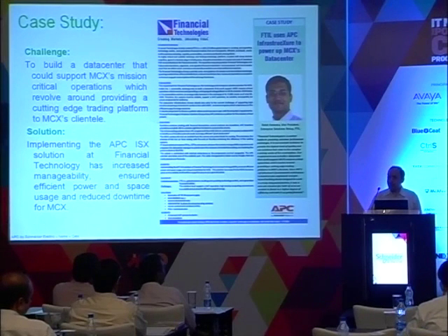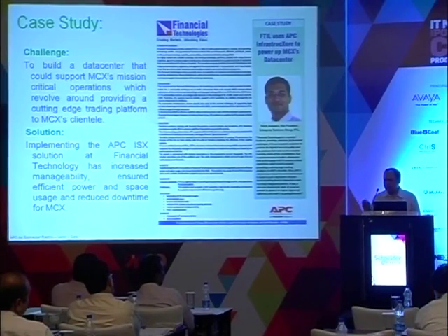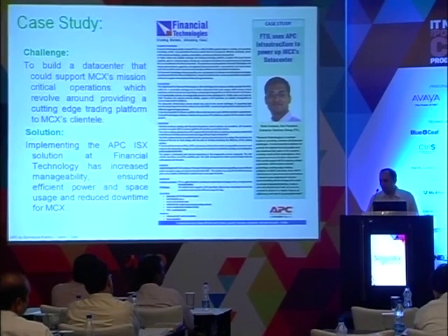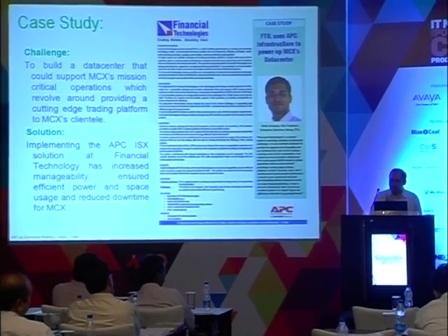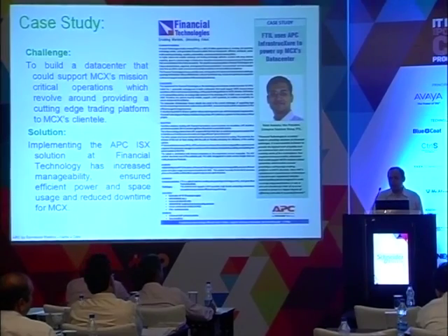So real-time PUE view is not very difficult to get. And again, it doesn't have to be with very fancy software. There are BMS systems possible today, where maybe you are already using one, where a simple add-on can get you a PUE view. But it is critical for you to start demanding that, because only when you demand, you will get. And then that will become the first benchmarking point to compare yourself with other data centers in your own region.